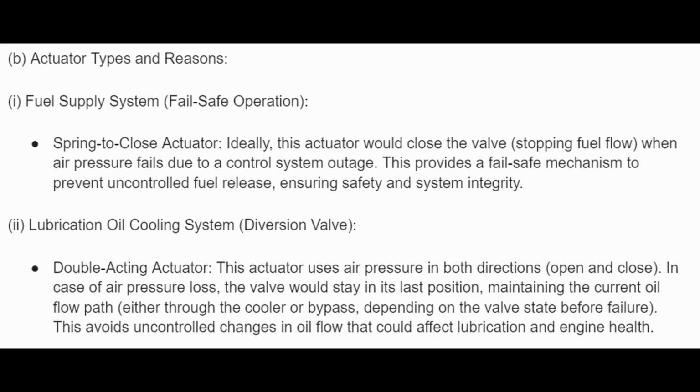B. Actuator types and reasons. 1. Fuel supply system. Fail-safe operation. Spring to close actuator. Ideally, this actuator would close the valve, stopping the fuel flow, when air pressure fails due to a control system outage. This provides a fail-safe mechanism to prevent uncontrolled fuel release, ensuring safety and system integrity.